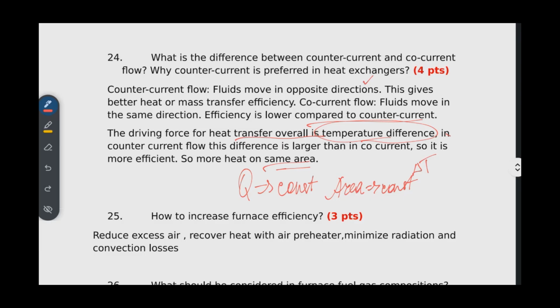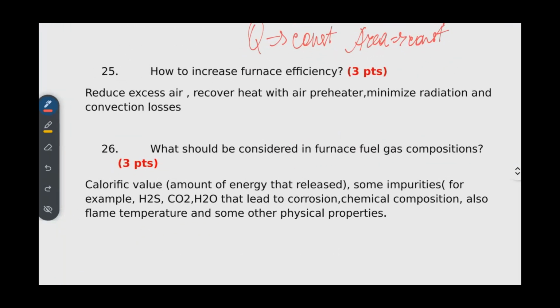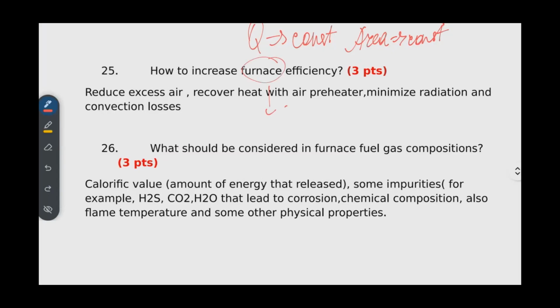So let's continue. How to increase the furnace efficiency? As you know, a furnace is also one type of heat exchanger, but it's a really big one, a furnace or fired heater, let's say. You can read about that mainly from API 560 or 660 in a detailed manner, to see the design and how it's constructed. So to increase the furnace efficiency, in general, you can improve your excess air control.